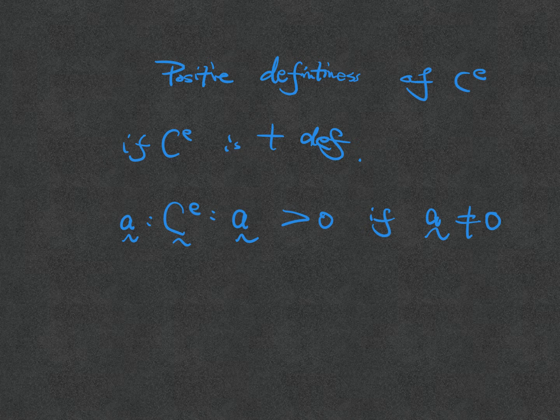Because if you add a 1/2 there, that would be exactly the elastic stored energy. And you don't want to create a theory where you store negative energy. It doesn't make sense. You can have no energy or you can have positive energy, you cannot have negative energy, at least not in mechanics. In literature, you can say I have some negative energy, but mathematically or in the mechanics world, the energy could be either 0 or positive. So CE being positive definite guarantees that you won't have those undesirable predictions that we know are not physical.